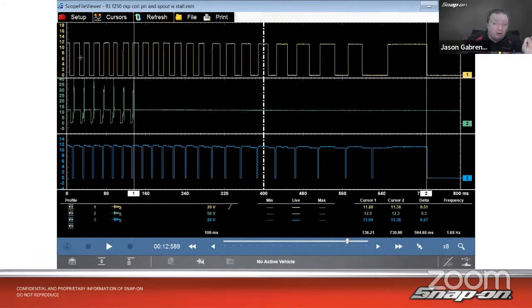Now, without having the scope, like I said, half a second. Who failed first? Within half a second of each other. We can see that plain as day using this method. But if I was just to rely on scanner data, I might never have found this, right?